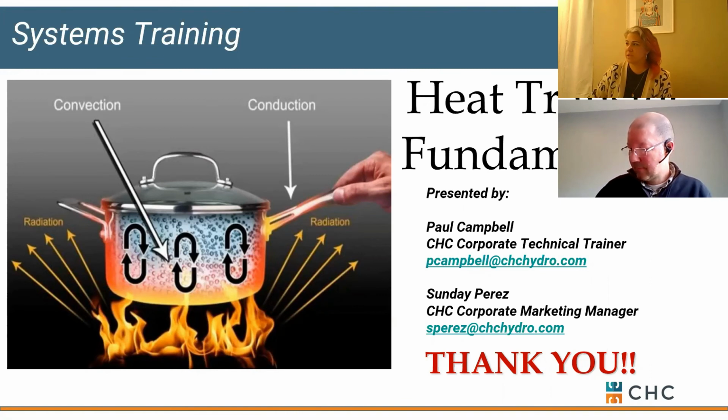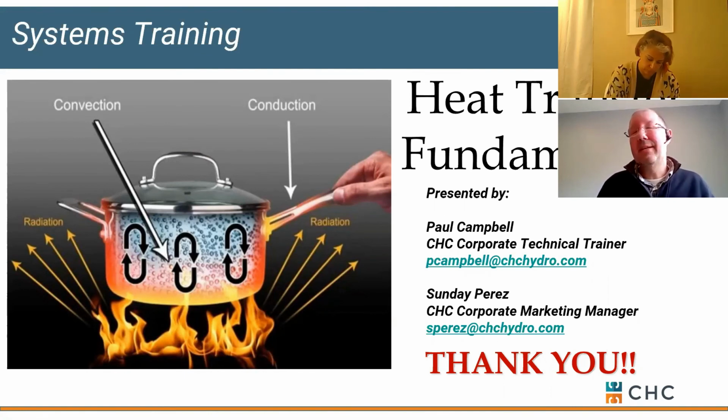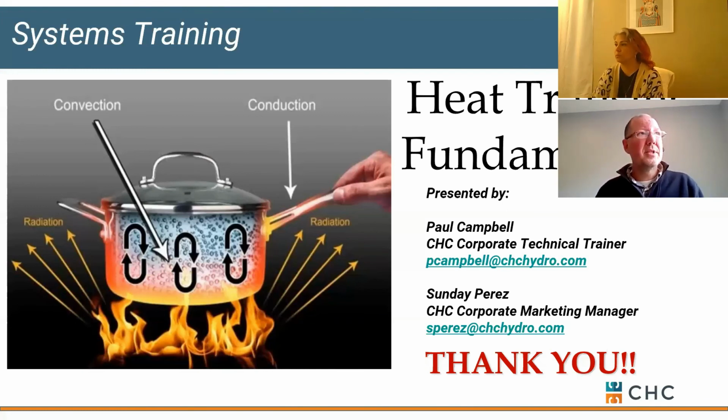How do you select the PSI drop for a heat exchanger? Oh yeah, good question. With a shell and tube, you really don't have to worry about it. Typically, you're looking at 5 to 10 feet max, and usually it's coming in less than that. On a plate and frame, you may get codes that require you at 8 to 10 pounds, but really your impact is on the pump that's getting selected, and ultimately horsepower, based on how much allowable pressure drop you can accommodate. We've seen some very conservative selections where you're at 5 to 6 feet of head, so you're talking about 2 pounds.